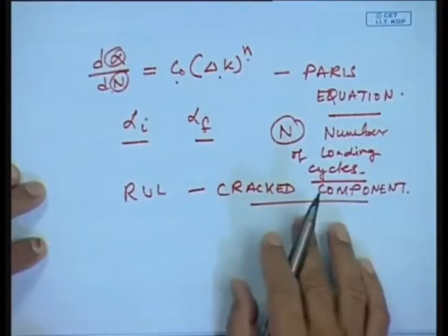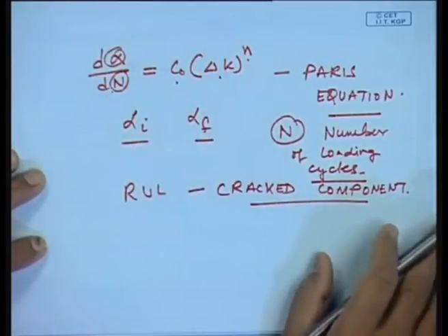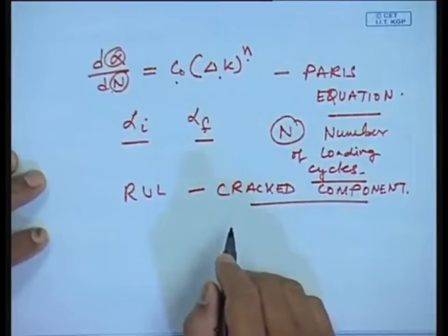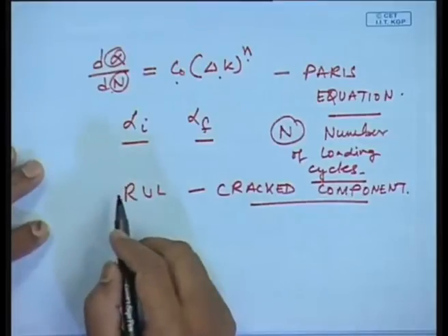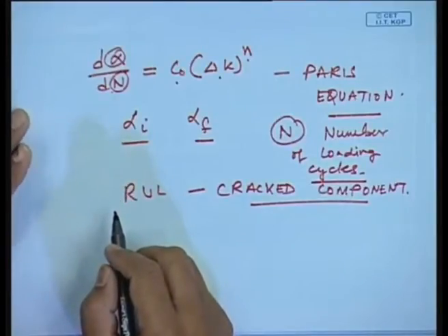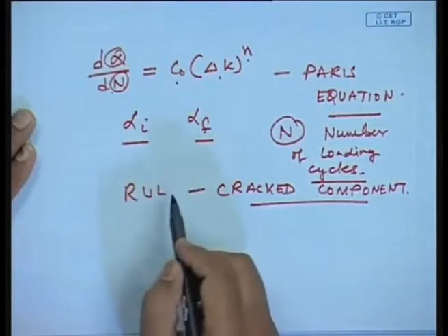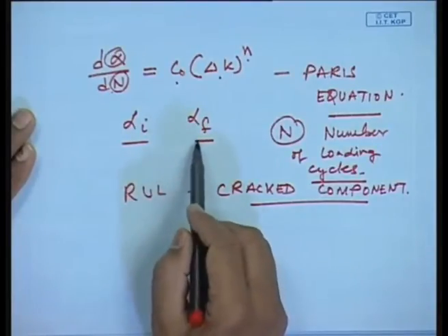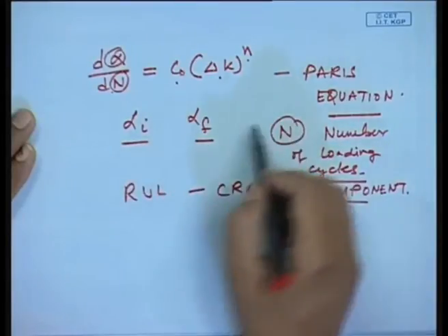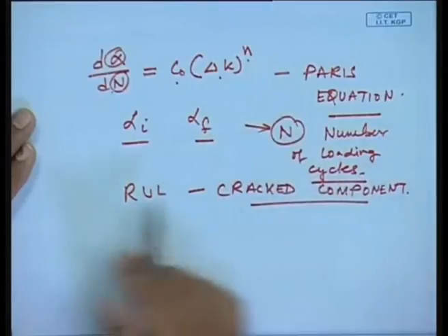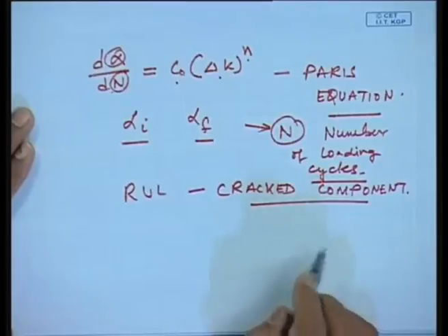Okay. This being a basic course, I will not go into details of all this because this will require a lecture on fatigue failure and fatigue fracture mechanics. But I just want to mention to you that such techniques are available for crack growth development, and once we know the final crack length which our machine can be subjected to, we can estimate the number of loading cycles and thus know the remaining useful life of the machine.